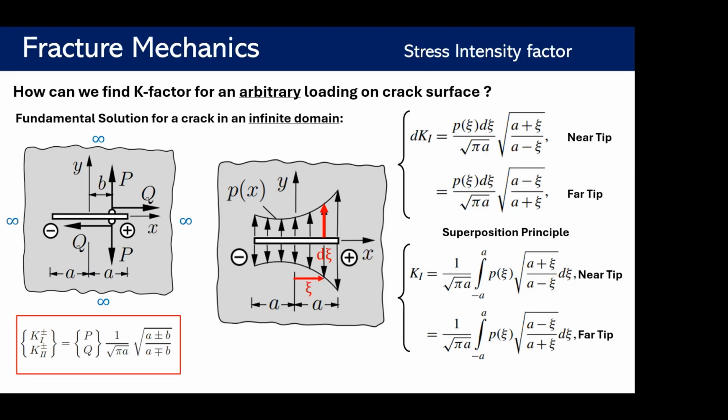For example, K on the right tip can be equal to the integral of the fundamental solution multiplied by p(x). p(x) is the intensity, or the function, of the distributed load acting on the fracture. And the integral should be from minus a to a over the crack length.